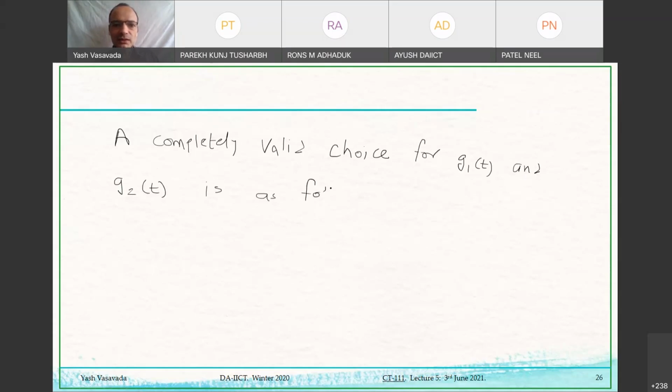So this will hopefully convey to you that the exact shape of the waveform is immaterial. Those two requirements have to be met. And so I will draw, as a function of time, this time axis. This is the time axis, and this is the voltage axis. So this is where I'm plotting g1 of t. And this is 0. I'll make this T_sym divided by 2, and this will be T_sym. So g1 of t is nothing but a rectangular pulse which starts from 0. So it is like this.